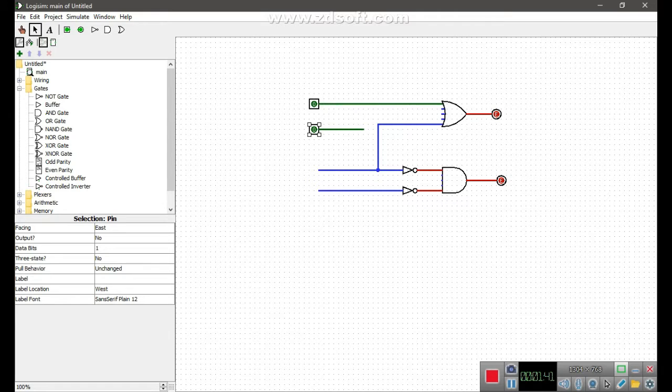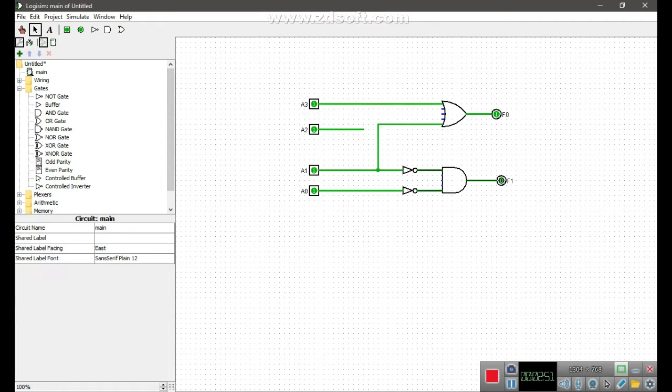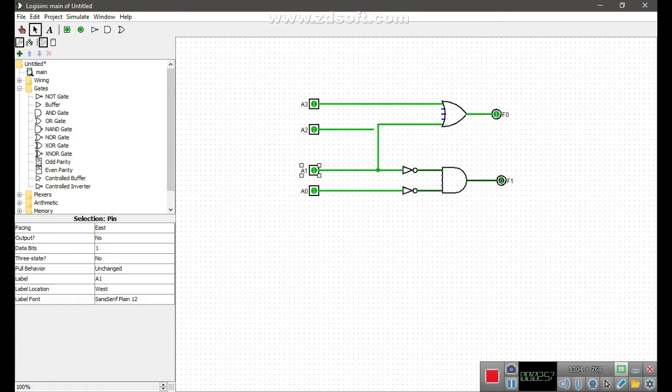Normally an encoder has a number of input lines, among which only one is activated at a given time, while a priority encoder may have more than one input activated. This means that encoders are used to control interrupt requests, responding to the highest request if two or more inputs are equal to 1 at the same time.